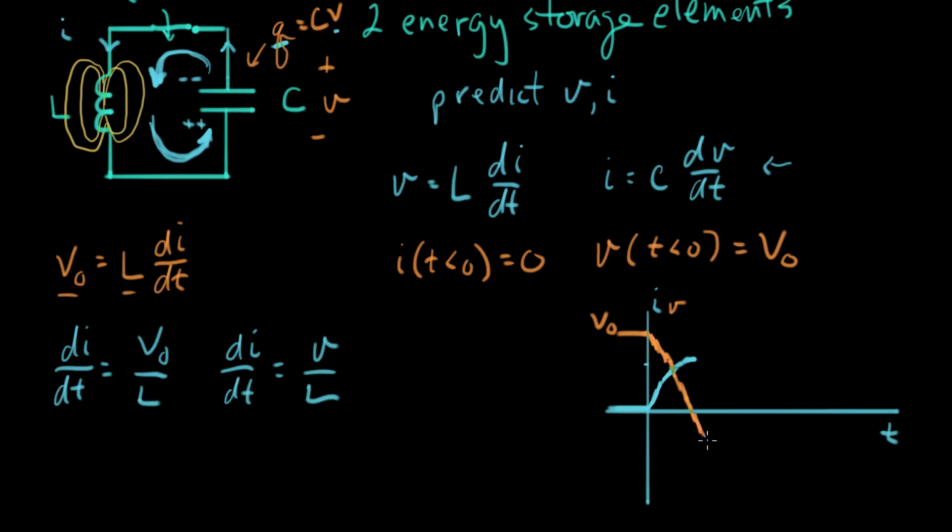And that tells us that we're going to have a negative voltage. It's going to start to grow here. I have a negative voltage. I go back to my inductor equation. This value of V right here, this is now negative. So that means the di dt has a negative slope. And a negative slope looks like it's sloping down like this. It starts to roll over and slope down. And a little less current means a little less slope on the voltage.